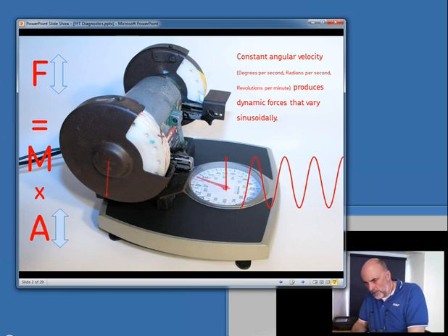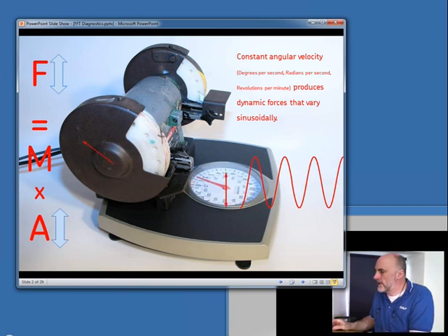And when we make our diagnosis using our FFT analyzer, one of the objectives is to get those forces down. So for example, if we measure excess unbalance, we want to get those unbalanced forces down. Therefore, we would go through the regime of balancing the machine, and there'll be a webinar next week on all of that, so we'll press ahead.